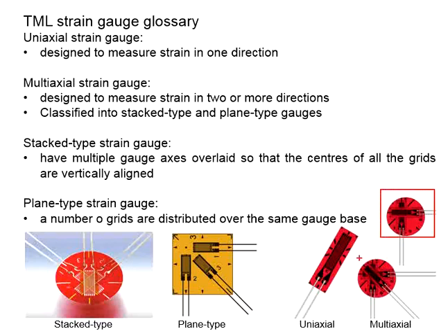These strain gauges can come in pieces, or if you really need to measure strain in various directions, you can combine several strain gauges, which are uni-axial, arranged in this manner, or this manner, or this manner. This can be done by using uni-axial strain gauges. This is conditional to careful installation of the strain gauges.